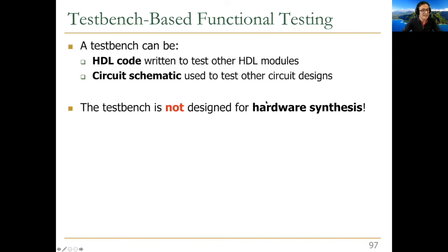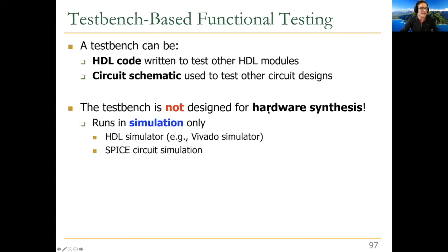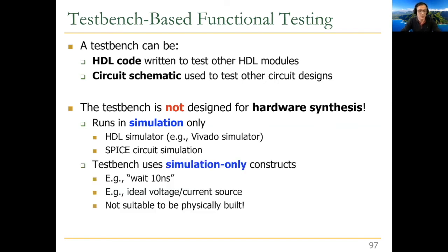Test bench is not designed for hardware synthesis. This is not something you synthesize. I mentioned this in the last lecture, but hopefully it's clear. The goal is really to run it in simulation only to check whether the functionality of your circuit is correct. And you can do it in HDL simulation. You can do it in SPICE simulation. Essentially, you can do it at any level of simulation that you are comfortable with, if you would like.